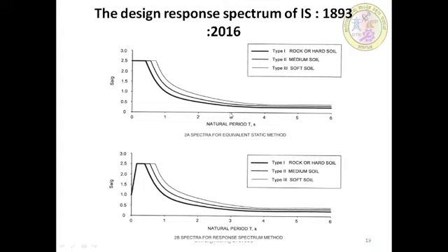In this case, we have seen the numerical evaluation, how it is to be done using the time step method, that is the linear acceleration method, using the Newmark beta method. We have also seen the concept of the response spectrum, the construction of the response spectrum, as well as how the three parts of the tripartite are included in one.